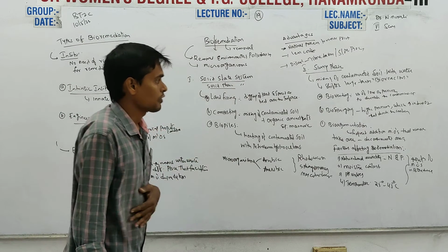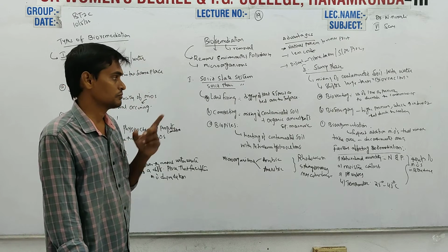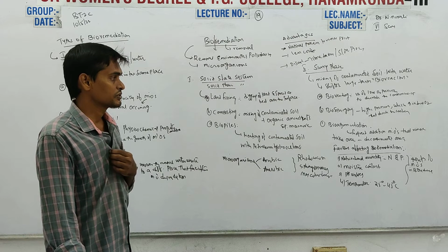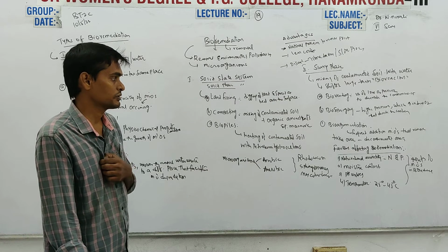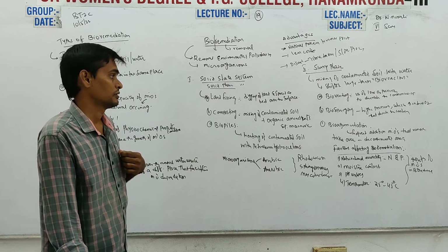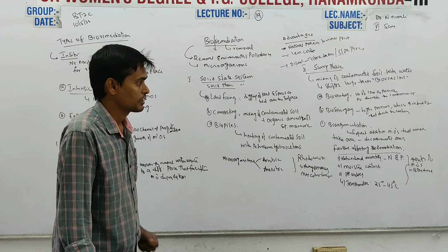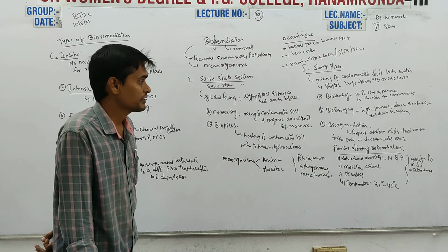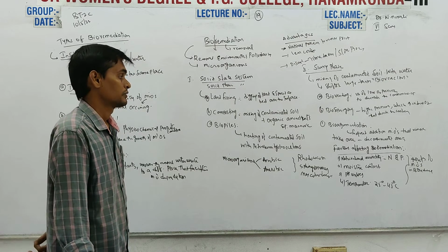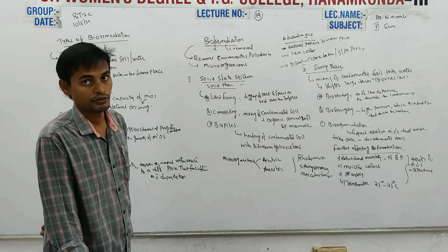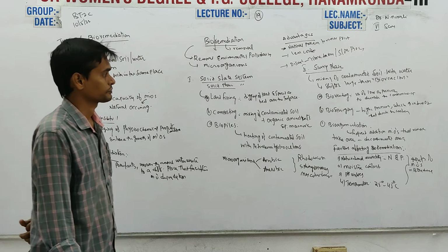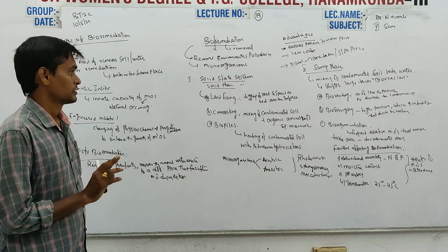Use of low oxygen pressure to degrade the contamination is bioventing, and use of high pressure, which increases the underground oxygen pressure, is biosparging, which degrades the contaminants. Next, bioaugmentation is the frequent addition of microorganisms to the tank bioreactors that can take over the contaminated area and decontaminate it.